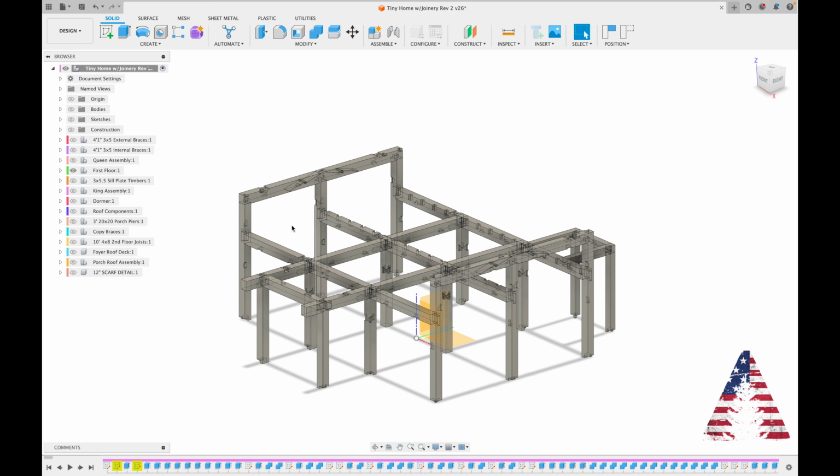We'll call this the x-axis that would go along this beam here. And those are all mortised and tenoned into these central posts all the way around. And then I've got these, which are called summer beams. They're splined. They're designed to go into place afterwards, so they're not mortised and tenoned. Once these sections are standing, these will drop in.